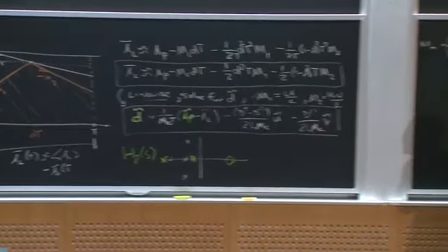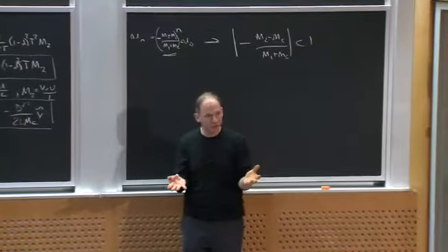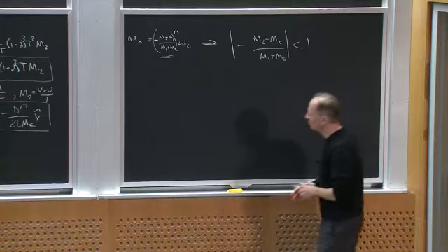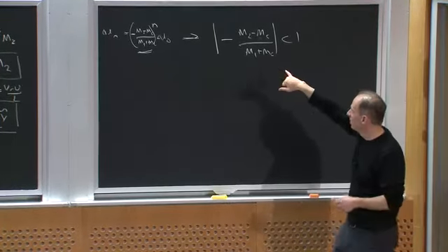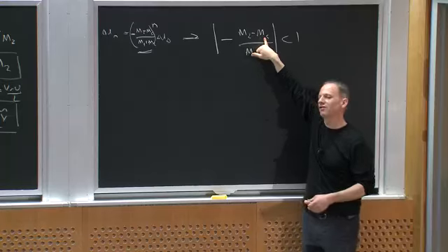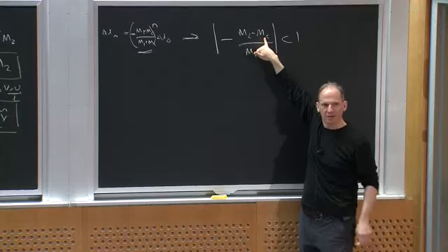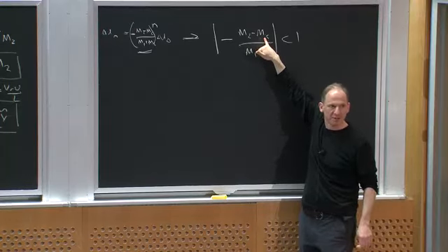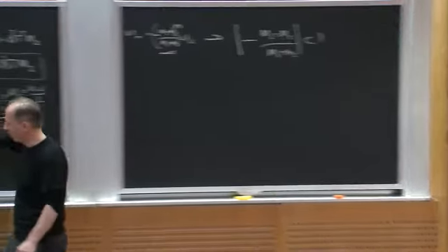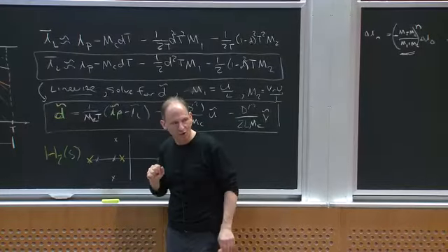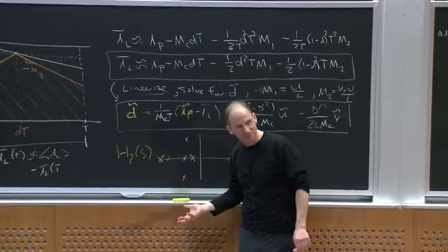Okay? So we would usually do this kind of ripple instability analysis and pick an MC that was big enough to make this settle down and make me happy, but not much bigger. And then I'd plunk that value into this average model and find out where my pole locations are and go on from there.